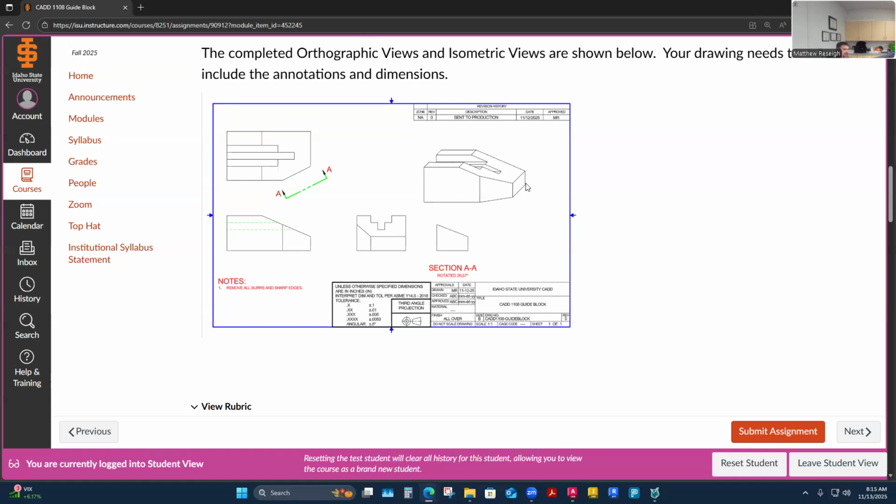So it's that cabinet oblique. I think it gets the name cabinet oblique because cabinet makers will draw their cabinets this way. It's just something we may or may not have ever noticed. So the front view is perpendicular to my line of sight, projecting away at 45-degree angles to half size going away. But this is drawn full size right here, the surface on my front view. That's called the cabinet oblique, so just pay attention to that. Page 511 in your book has some of that explanation.